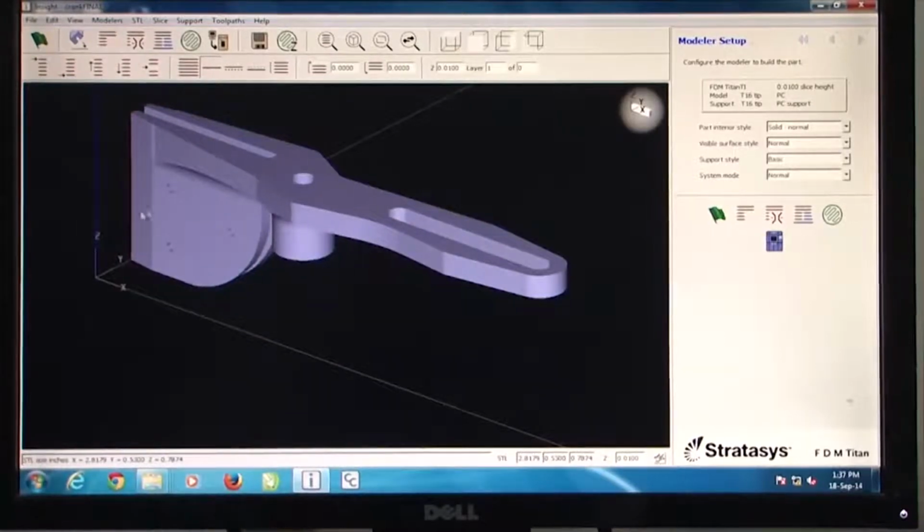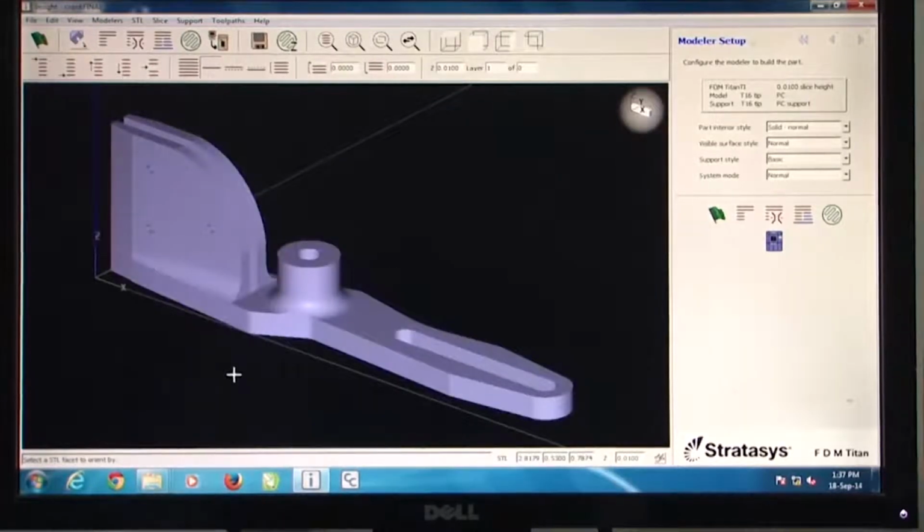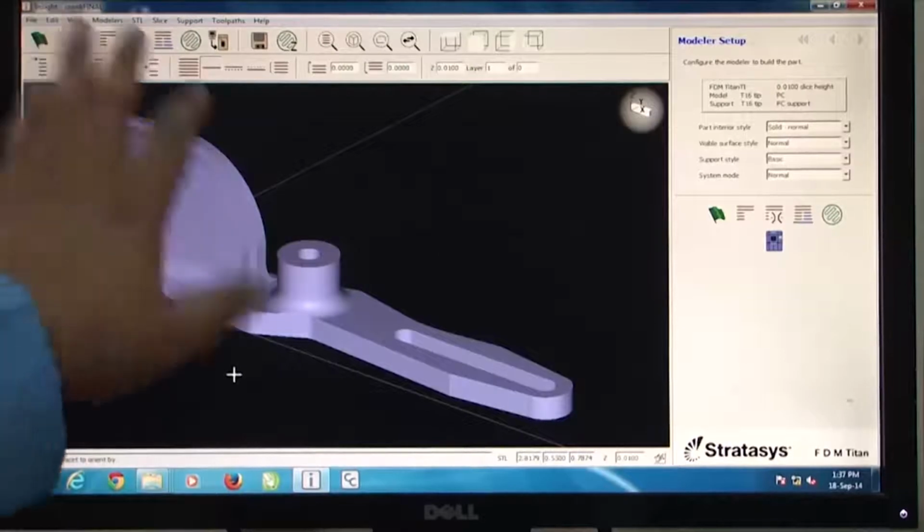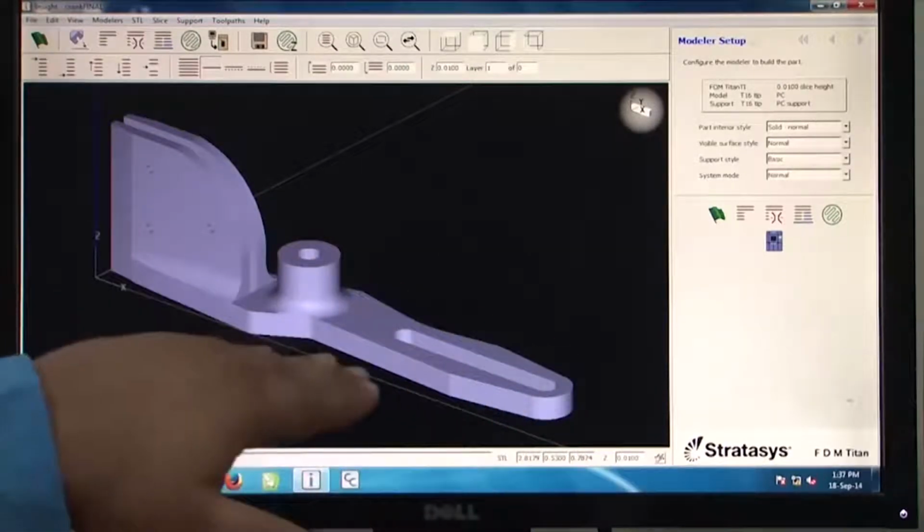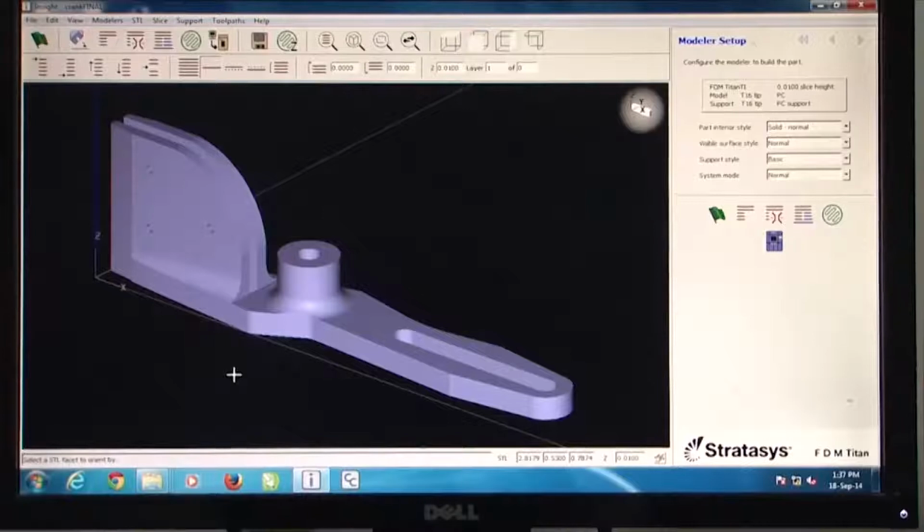And so, I am going to make the front portion of the part here the bottom. Okay. So, I am going to see what is the bottom. Okay. Take this up and then take this cursor all the way to this portion. So, this comes on the bottom and the part topples. Okay. So, now you can see the part has toppled and it has lain down on a flat surface, which is more appropriate for the purpose of doing RP or rapid prototyping.